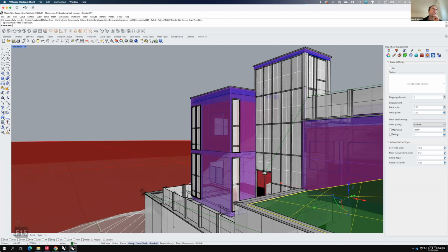All right, let me see if I can do it over here. Okay, so I thought it showed up here in my properties. It hasn't showed up there yet, but in the V-Ray toolbar here, there is a tool that looks like kind of grass sprouting out that is Add Fur to Selection. I'm going to go ahead and click on the Add Fur to Selection.